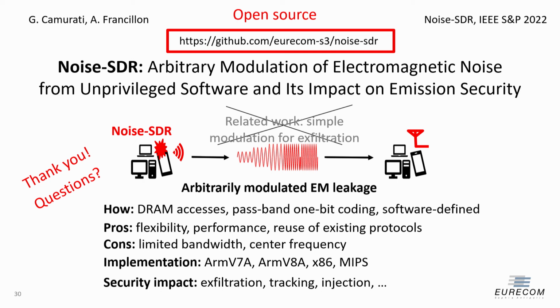Oh, yes. Okay, so I think the key point in the threat model is that we're considering a piece of software that should not have access to any communication interface, and we give it a communication interface. And then what we are doing, this is classics of Tempest, but what we are doing is making it easier. So for me, the practicality, all the limitations in terms of difficulty of placing the software on the device or having a leakage there are similar to classics of Tempest, but where we help with practicality is that it becomes very easy now to transmit. And all the techniques like error correction and interleaving, they really make everything more robust and achieve better performance.